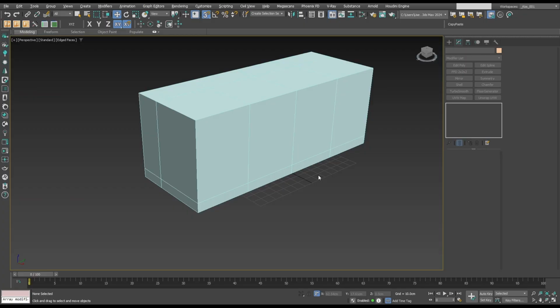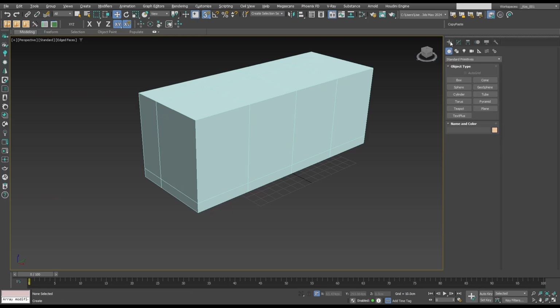The island's metal framework is built from a square hollow section. It's a 2.5 by 2.5 centimeter cross section. It's gonna have, as we said before, some vertical posts and some horizontal beams. The beams are gonna be both in transverse and longitudinal directions.